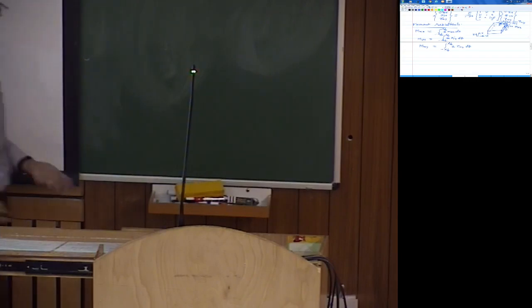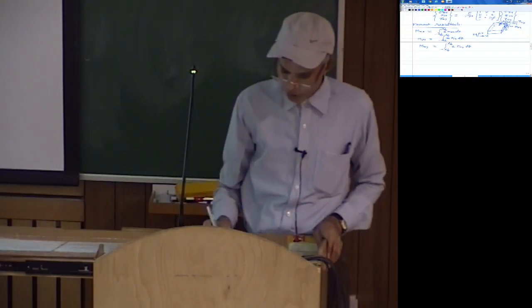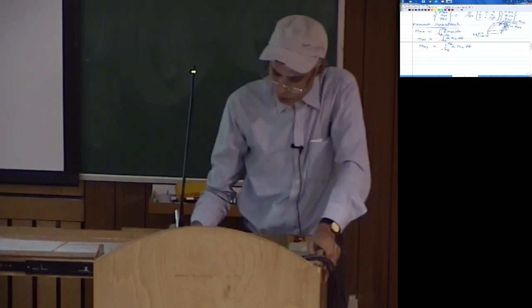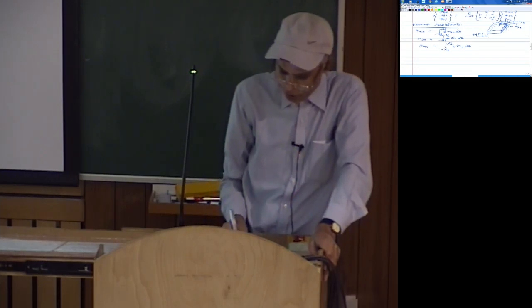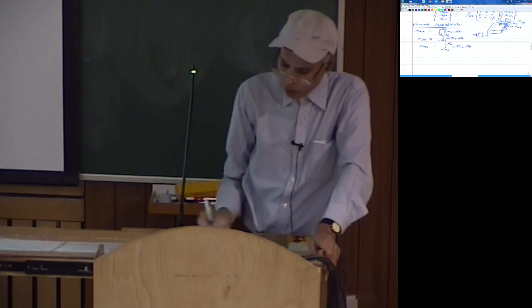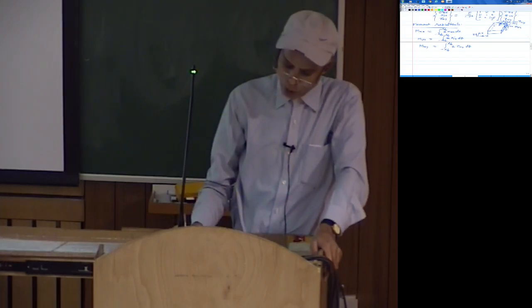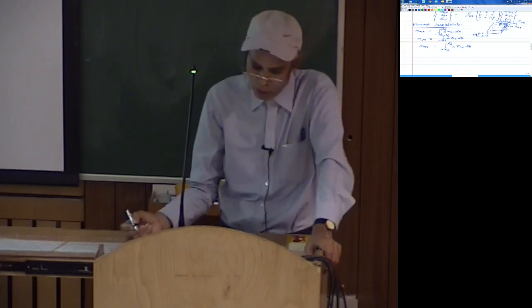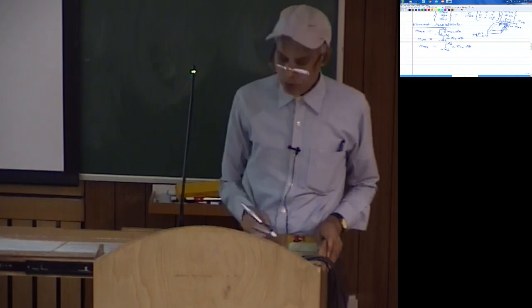They can be positive or negative depending on the problem, but the positive sign convention for this is that mxx is the moment about the positive y axis, myy is the moment about the negative x axis, and mxy on the x face is the moment about the negative x axis, whereas myx on the y face is the moment about basically the positive y axis.